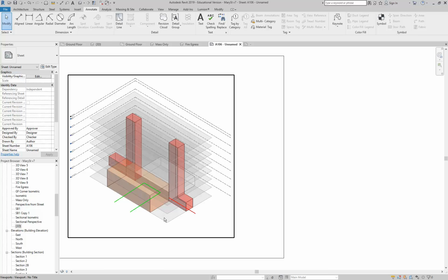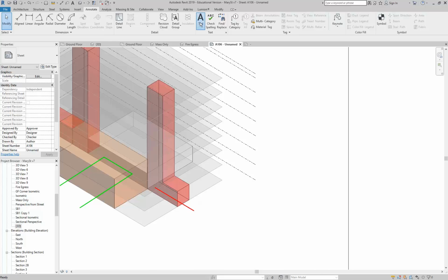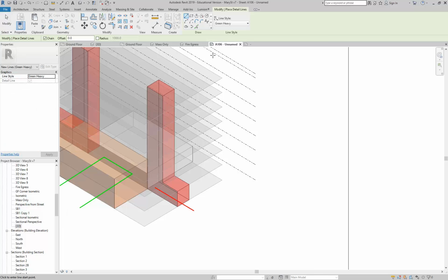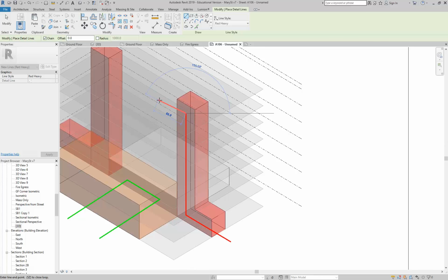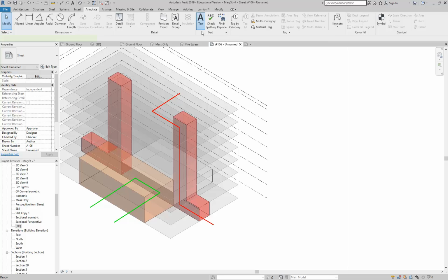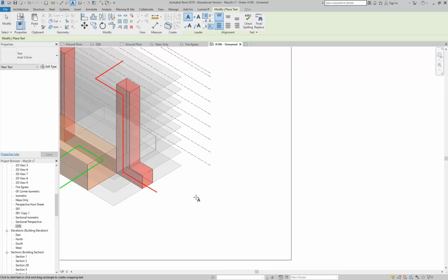And so you can do those diagrammatic sorts of lines, and then you can also label everything. You can do text in those views as well. So maybe if it is for fire egress, then you'd have lines that show the path of travel, and maybe on one level you'd show your distances. It could get a bit complicated, but that's something you could do. And then again, with text, the text tools in Revit are pretty good. Not as good as InDesign or Illustrator, but still pretty good.